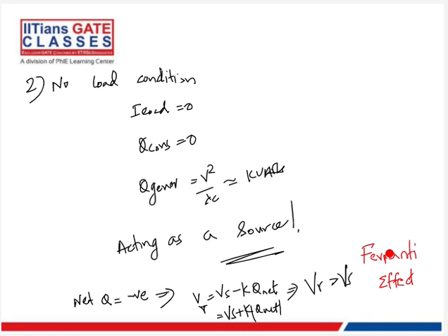Right? It's called the Ferranti effect. So basically, when you are turning on a transmission line, like when you're introducing a transmission line, at that point the voltage at the receiving end will become higher, and this will cause the traveling wave phenomenon and all those things, right? And usually, what we do when we are actually powering a line is connect the reactor at the receiving end so that this voltage does not go up. That's where we use reactive shunt compensation, right?